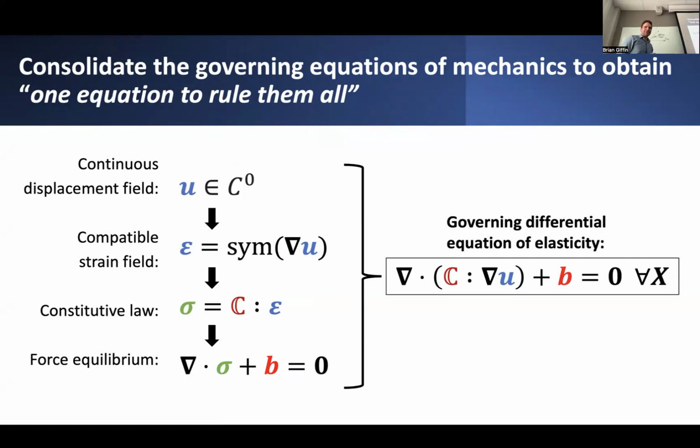And really the only field that we should be using to represent this solution, the thing that we're solving for, is just the displacement field. What does the deformation look like? If you know how this body has deformed, expressed in terms of the displacement field, then you know everything else. You don't necessarily need to treat the strain field and the stress field as independent solution fields. That's convenient if you don't want to independently figure out what those need to be. Most finite element programs and other automated solution approaches for solving these types of problems take exactly this course of action.